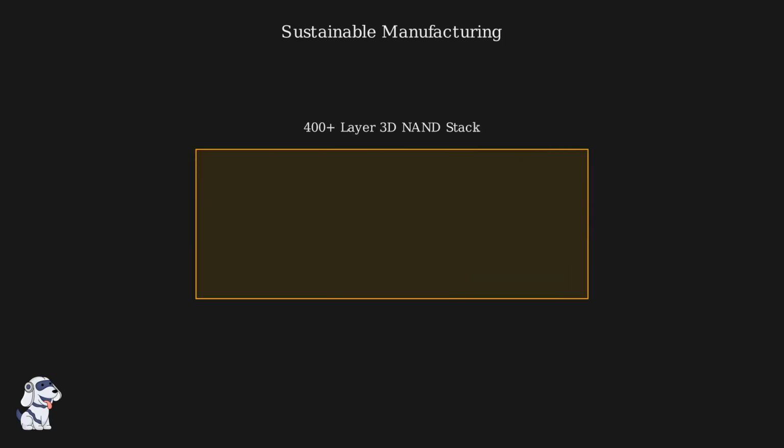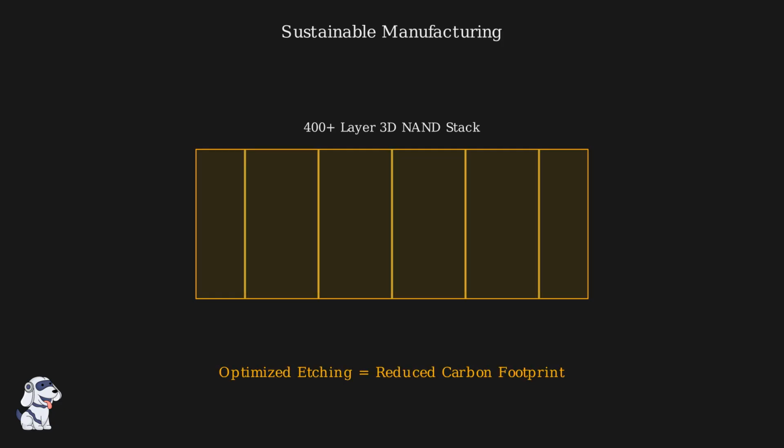for all performance-critical infrastructure. As we stack NAND memory to 400 layers and beyond, the manufacturing process faces a sustainability hurdle: the creation of deep, precise holes known as vias. Traditionally, these deep vias require massive amounts of energy for etching. The industry is now evolving toward high-precision plasma processes that reduce energy consumption and chemical waste. By optimizing the gas flow and plasma stability, semiconductor manufacturers are significantly shrinking the carbon footprint per wafer. This efficiency is critical as demand for dense AI storage continues to grow.